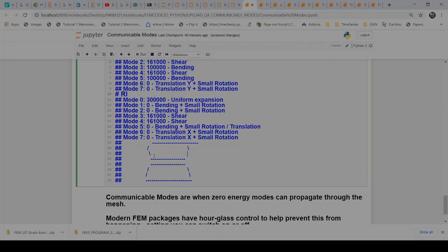So there's now another element here at the top that's also bending. You see that? Bending. My ASCII art is not bad. Bending. So if I have an element here that is in a bending kind of mode, and I've got an element here that is in a bending kind of mode, and they're on top of each other, what does this look like? It looks like an hourglass.